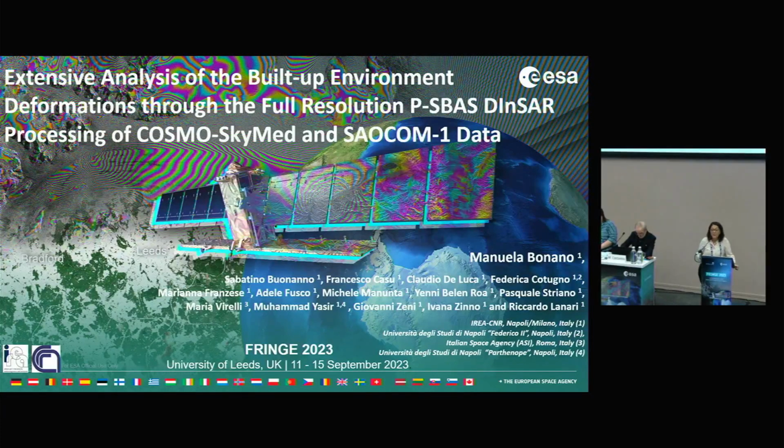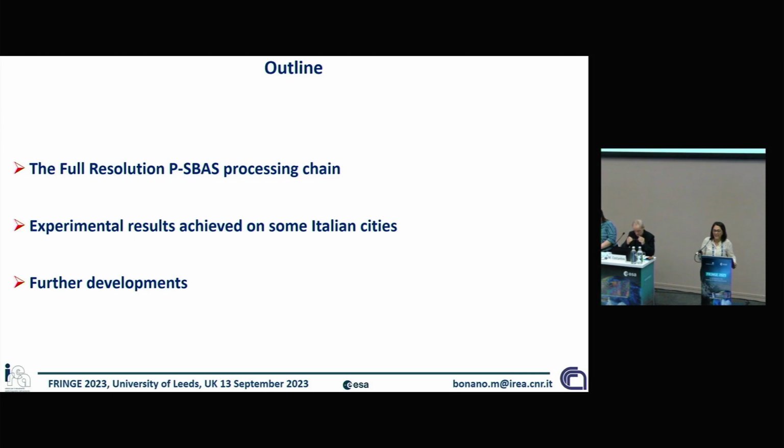And the main results I'm going to show you are relevant to the exploitation of large multi-temporal SLC data stacks relevant to X-band COSMO-SkyMed datasets, but I'm going to show you also the preliminary first results relevant to SAOCOM-1 data, L-band SAOCOM data. So we will just say a few words about the full resolution P-SBAS processing chain.